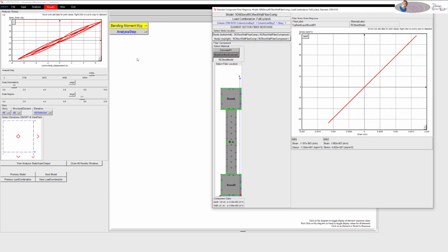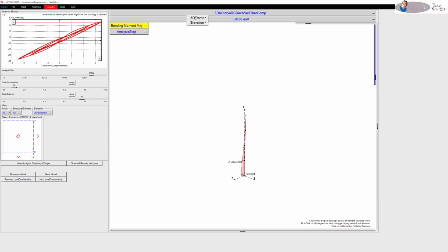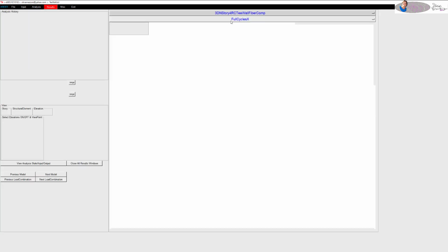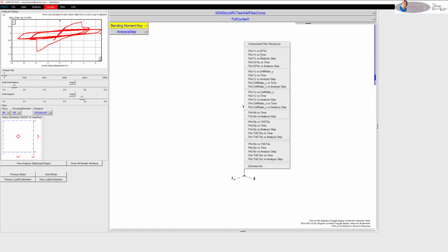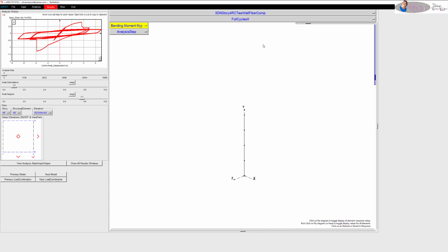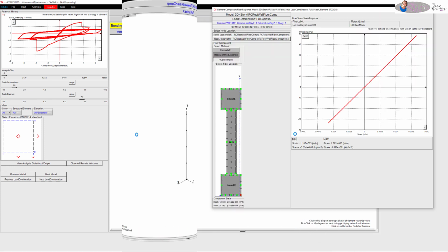But sometimes you get more interesting structures. Maybe if we look at a C shape, or let's look at the T wall. That's for sure going to have something interesting. There it is. Yeah, this is a good one. So let's go here. If we look at the fiber response, there's definitely some stuff happening, but likely it's more the concrete. I literally just came up with random numbers, so it's not a well-defined section. The axial loads are just random, but I tried to make something until it gave me something nonlinear.